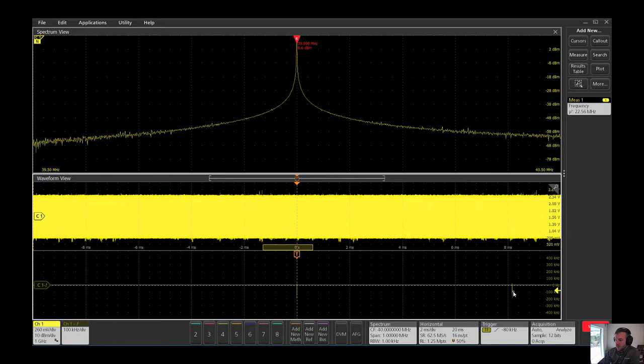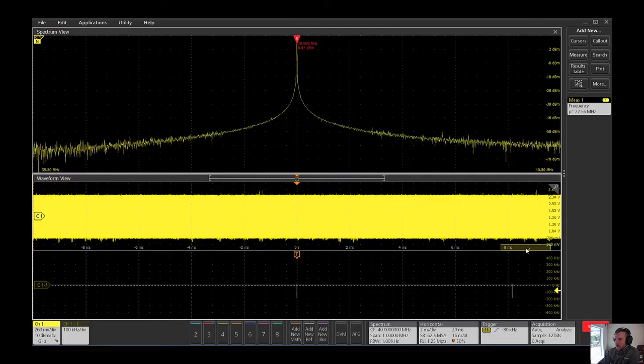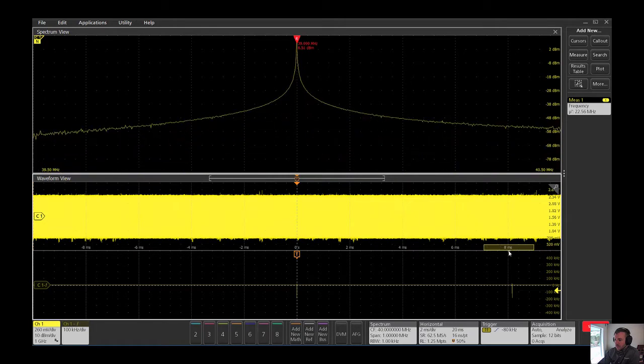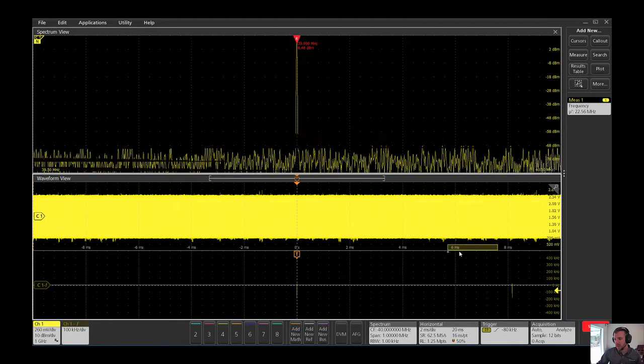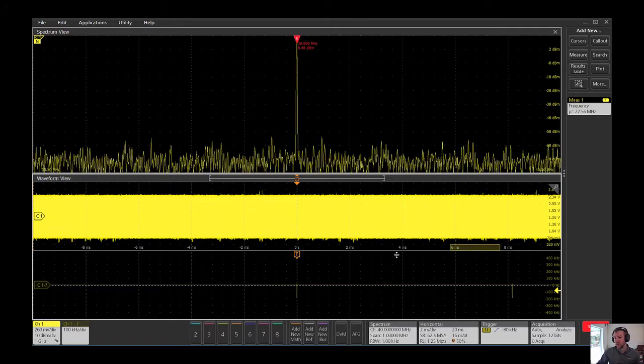And it looks like it happens over here again about 8 milliseconds later. Let's drag spectrum time over there, and the same behavior happens a second time. I'm not going to do the full demo, but you can set this up on 8 channels. You can have 8 independent selections for where spectrum view is, and you can have 8 different center frequencies.